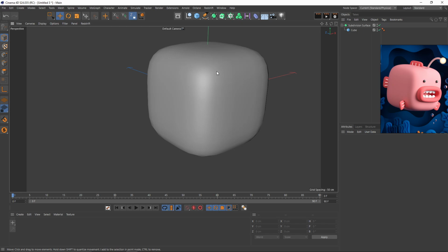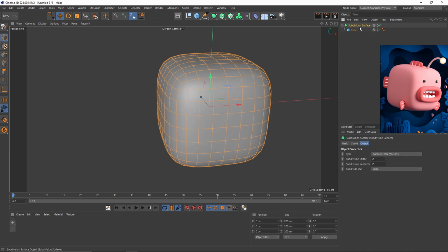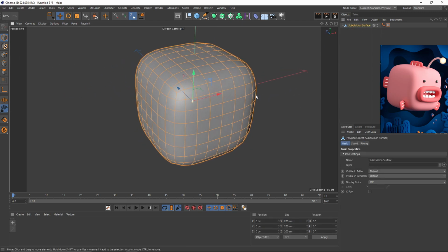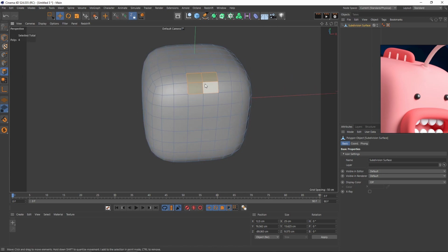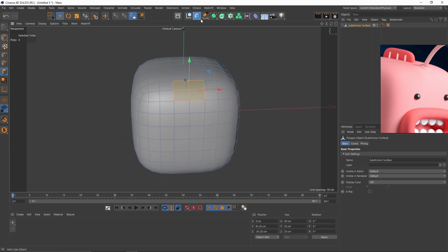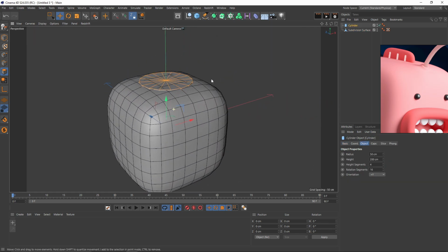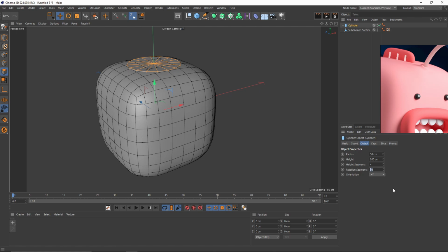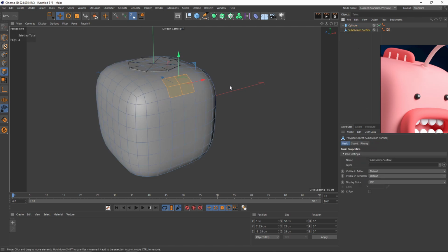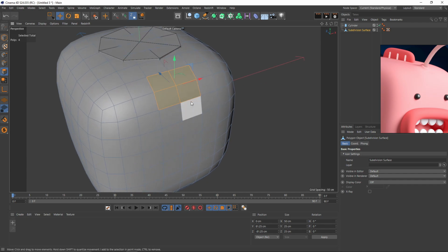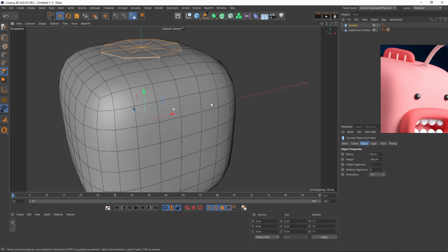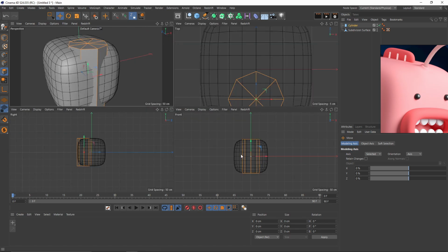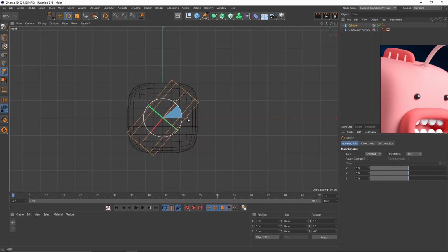And it is nearly the same thing. I will check my subdivisions. All right, looks good. I can make that visible. Now let's do that hole. I think it's somewhere around here. We will need a reference. I will create a cylinder, set the rotation segments to 8 because, you know, I have selected this for polygons, which will need a cylinder with 8 rotation segments. I will rotate it.